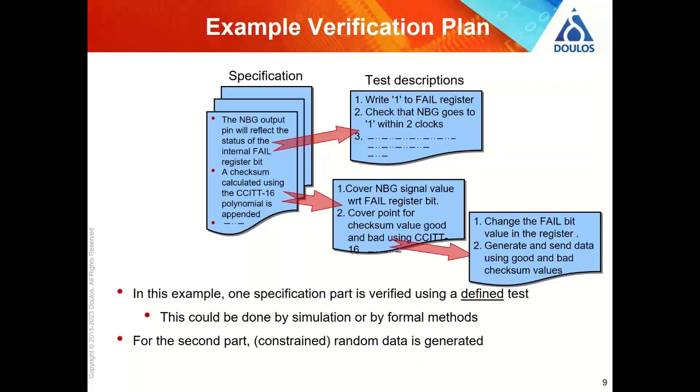So we could have an example here where we've got an output pin that needs to reflect a particular register bit. So we could have a structured test where we're going to write a sequence of values to the inputs and check to see if we have the expected behavior. Okay, that's perfectly valid. We could run that test. Somebody else could read the verification plan, rerun that test, and confirm that it's working as expected.